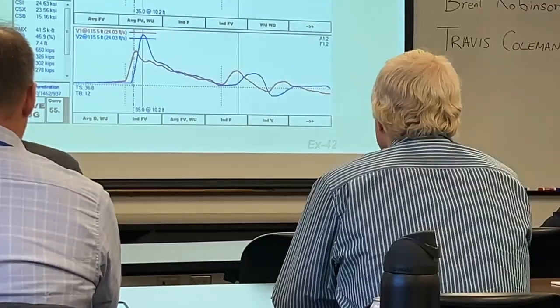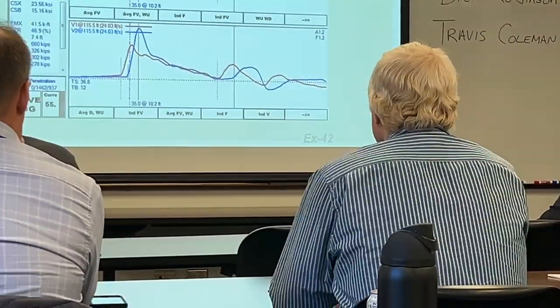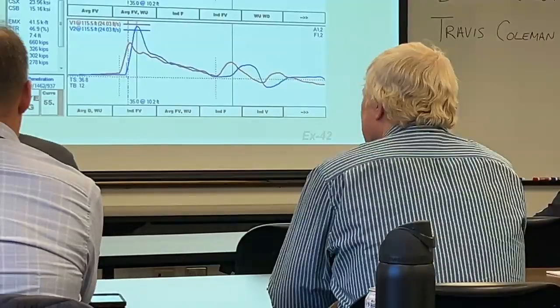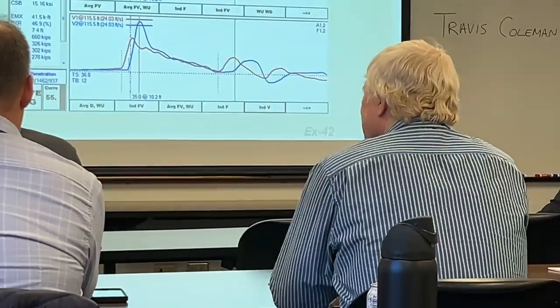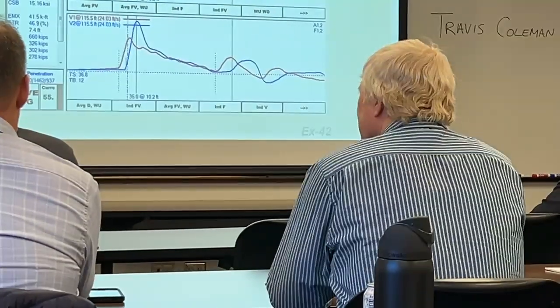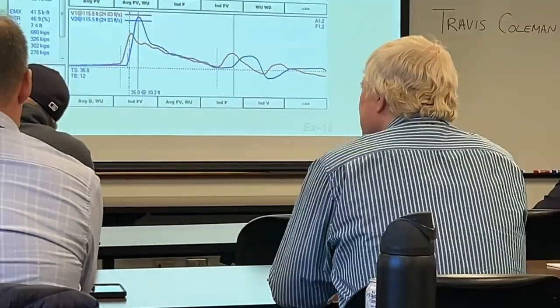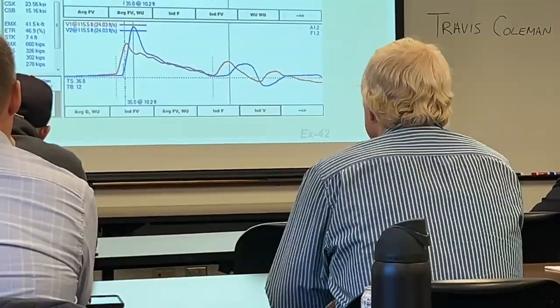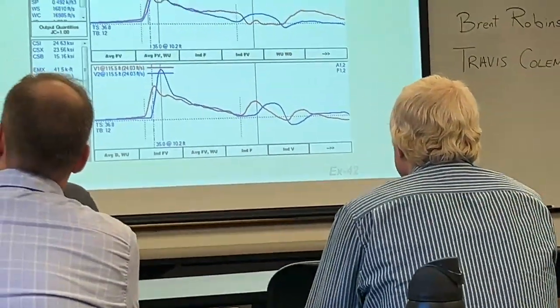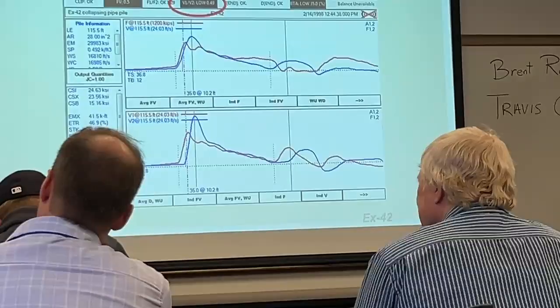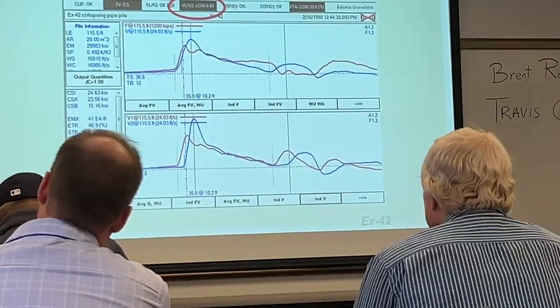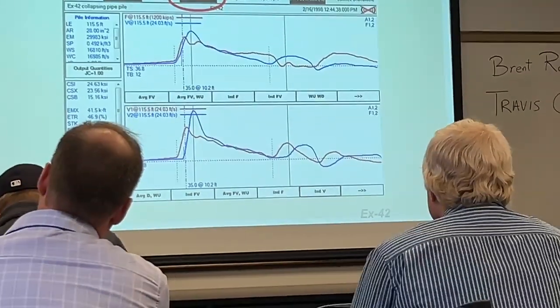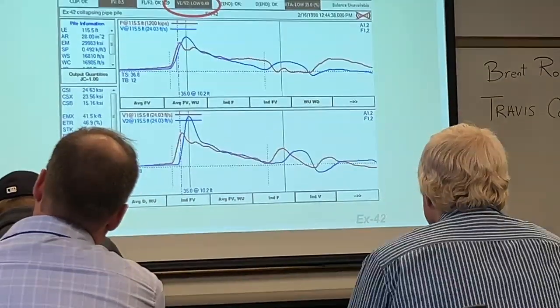What's happening? So remember, our accelerometers, you're sitting on 1 bolt. And if that accelerometer has some slop in it, if I put a bolt through that hole, the bolt moves with the pile. But if the accelerometer is loose, it's just going to sit there. When the bolt hits the bottom of that accelerometer, it's going to yank it down. And that yanking is this sharp increase there. What can I do in this case?